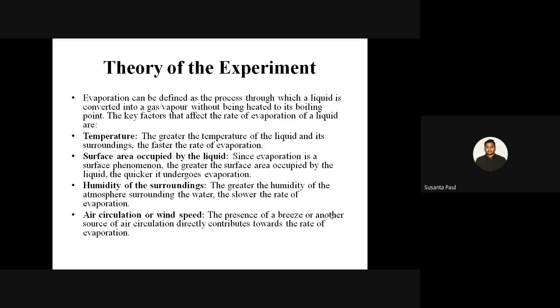Now the rate of evaporation is controlled by the rate of heat transfer. When heat is applied to the solution, the movement of the molecules increases, and the molecules present on the surface overcome the surface tension of the liquid and evaporate. So the solvent molecules are vaporized from the surface. We can say the evaporation process is a surface phenomenon.